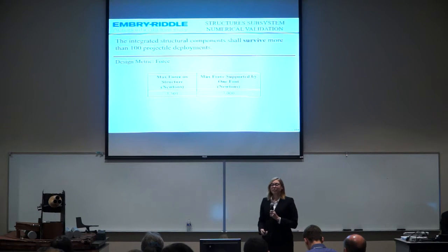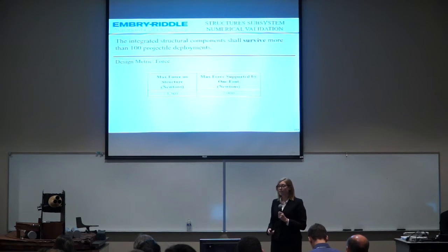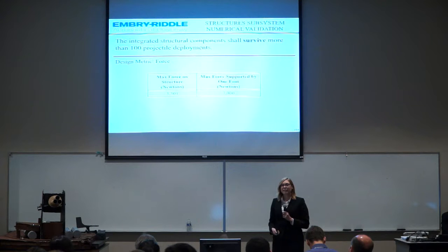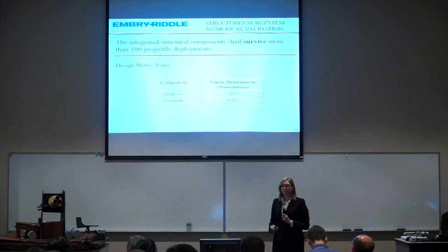The first requirement I'd like to look at is the integrated structural components shall survive more than 100 projectile deployments. In order to validate this requirement, we'll be looking at individual pieces of our structure and making sure that each individual piece can withstand the missions. So the first piece we looked at is the feet. Each foot can withstand a force of 7,000 newtons. The maximum force that will be put on all 4 feet at any given time is 3,504. Therefore, the feet will not break.